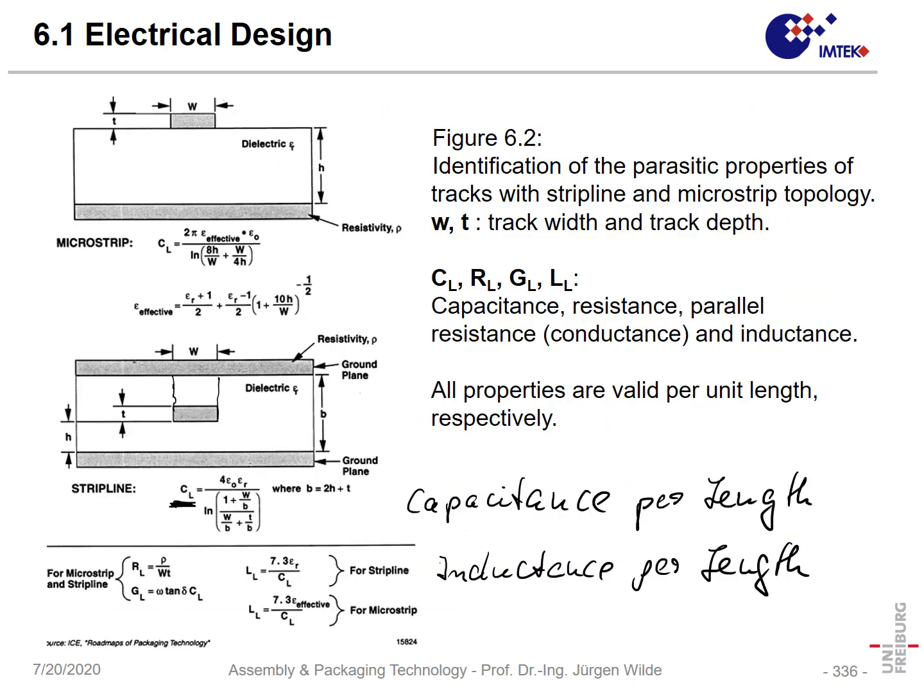And the main reason it acts is that that conductor acts by the recharging of that capacitor. So always when we load that capacitor and uncharge it, we have the so-called dielectric losses. And these losses increase with the frequency of our signal.